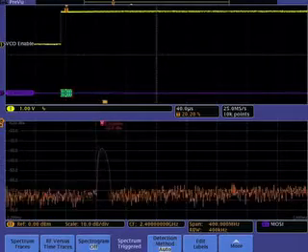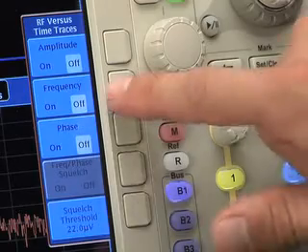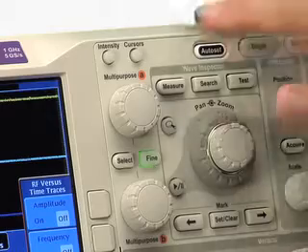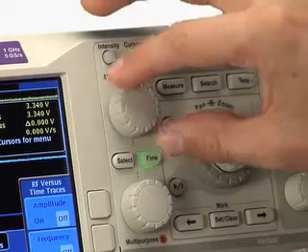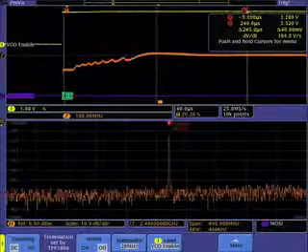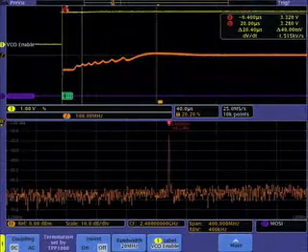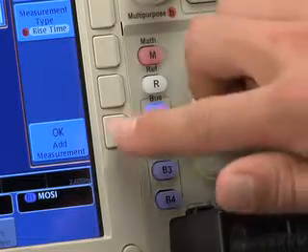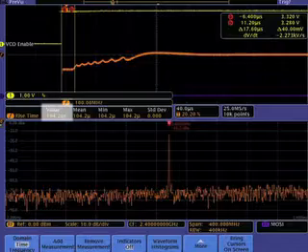Now a frequency versus time trace is added to enable fast and easy timing measurements of the PLL. By simply using cursors, you can accurately measure the time delay. Then a simple rise time measurement can be made on the VCO's RF output to measure the settling time.